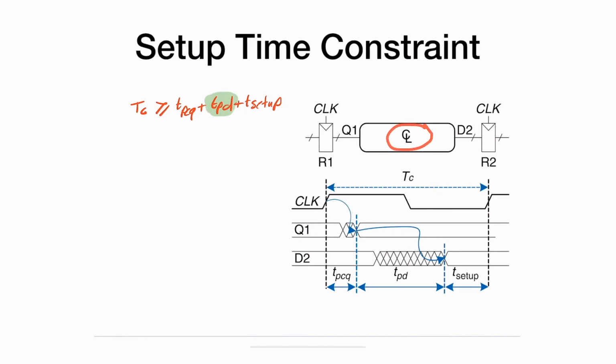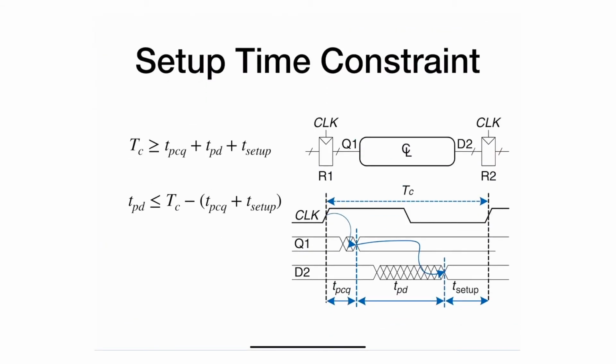So the only control you have here is how slow, or what's the slowest I can get from here to here, from the input to the output of the combinational logic. You might have to change your combinational logic design to satisfy that. Sometimes you're going to see that some people rearrange this equation. These are just written again cleanly. You rearrange this equation and it tells you that in order to do this, you can constrain or construct a combinational circuit that has a propagation delay less than this particular value in here.